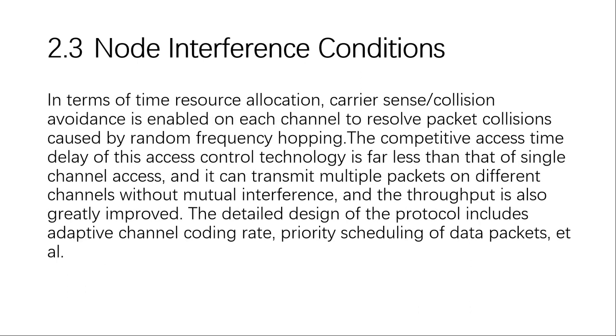In terms of time resources allocation, carrier sense collision avoidance is enabled on each channel to resolve packet collisions caused by random frequency hopping.